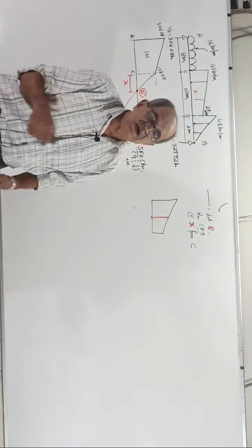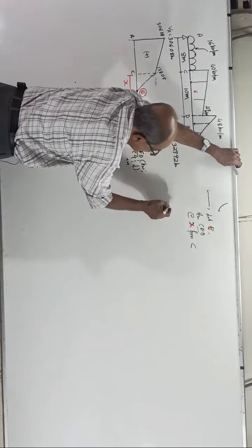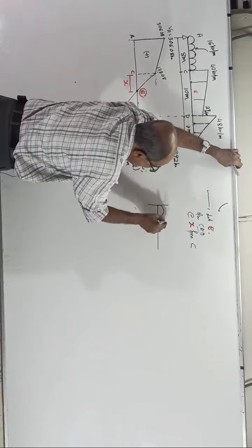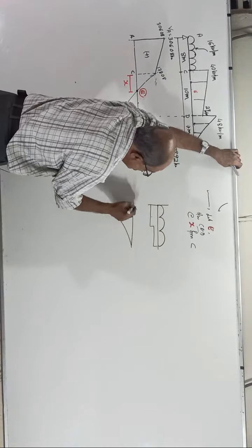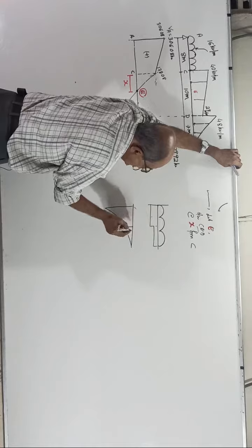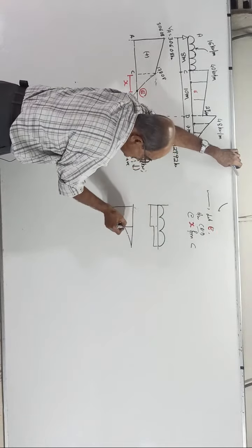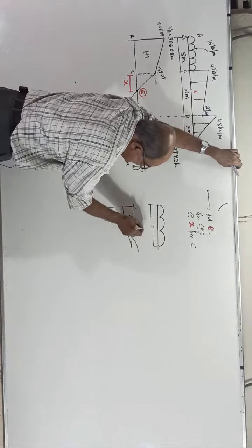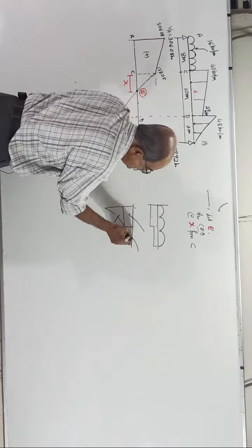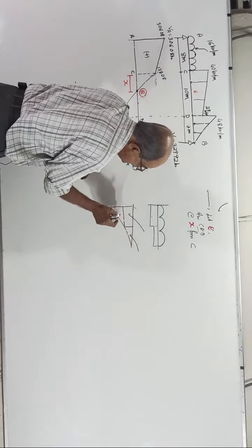But of course, sometimes I have seen blunders are made. See, cantilever beam of this type, BMD comes this way. The change of EI is there. Now, what they will do is, they will divide this like this, and then one parabola, one rectangle, one more parabola. These two are correct. This is parabola.